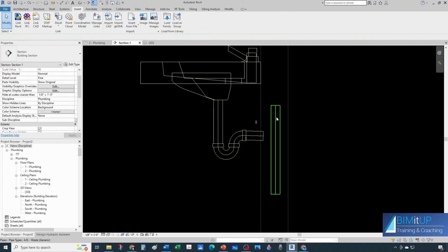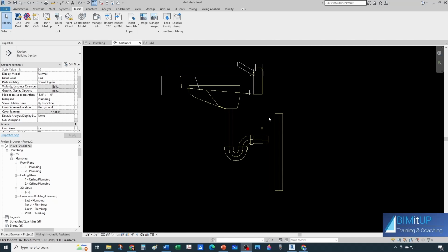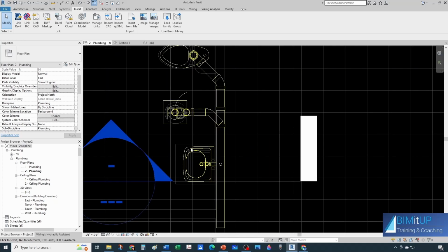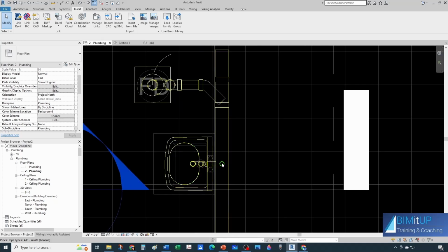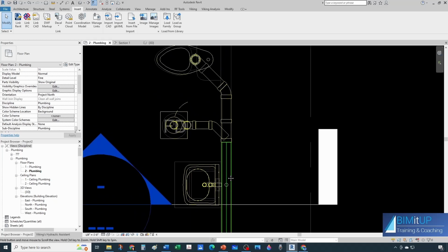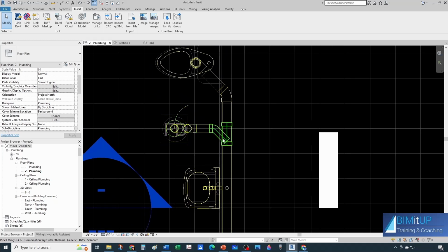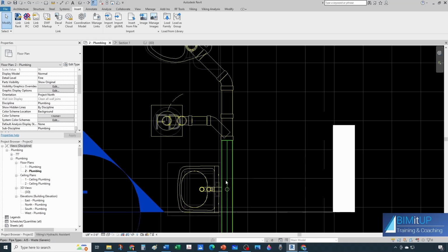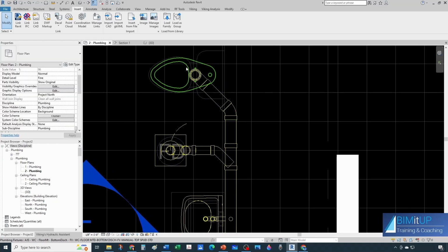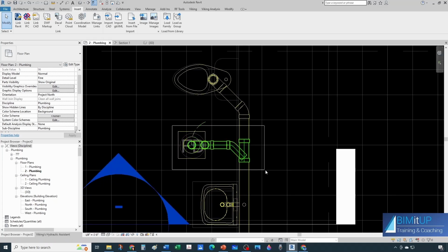our stack. But then if we were to create a stack right here, what would be happening is that this would be venting this line, but then this drain would be connecting before venting, and that's not what we want. What we actually want is the vent to be right after the toilet, right here. So let's go ahead and make a little bit of room for that.